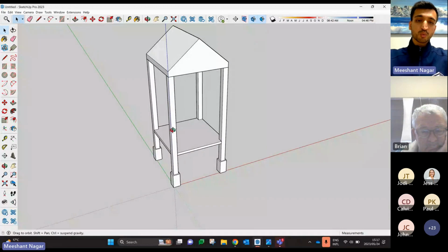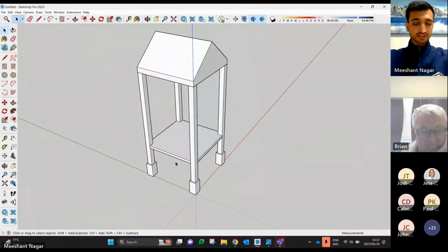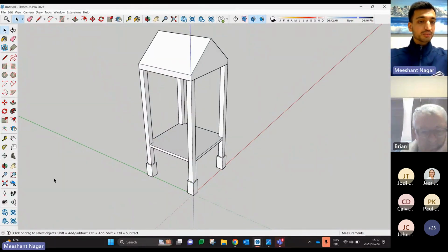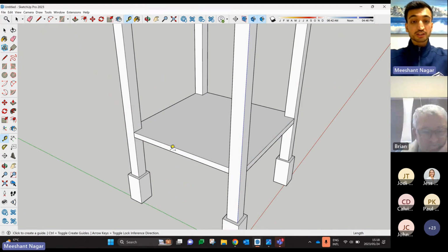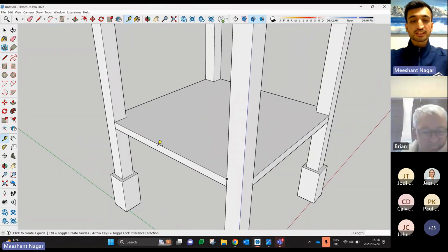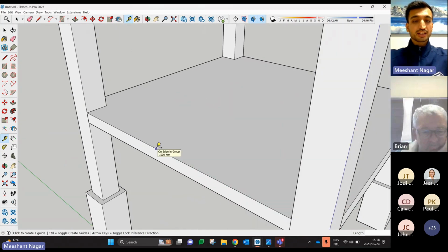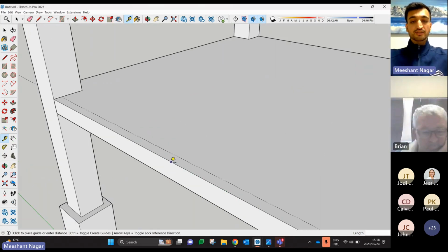Moving forward to maybe putting in a wall over here for the side of the jungle gym, I'm going to be introducing a new tool. It's called a measuring tool. The tape measuring tool, like Move, has multiple purposes, not only to measure the sides of things, but also to create geometry for yourself in the form of construction lines. So for instance, if I need a wall over here, I can drag this line out. Let's make it 25 mils. And then I want to drag another line out from there. Let's say 75 mils out.